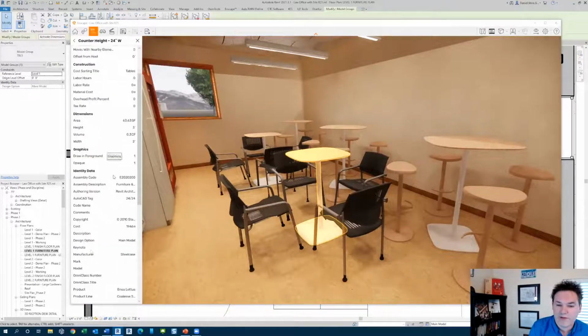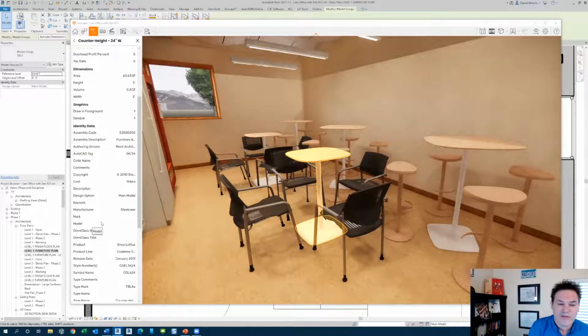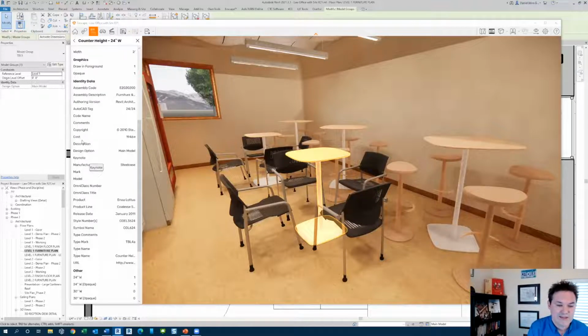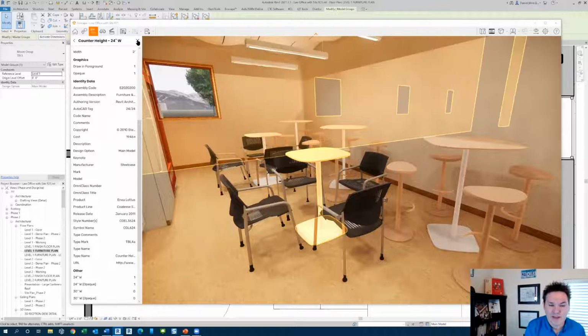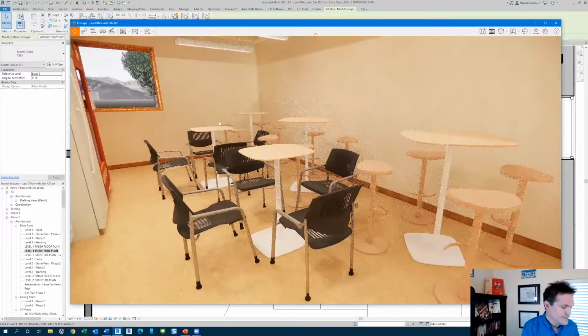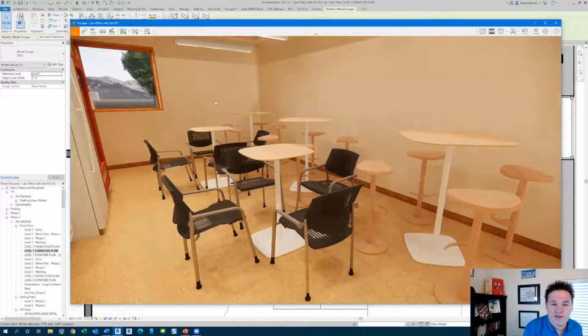And again, we can use the BIM information to verify that. This is a great thing that you can do when you're presenting to a client, if they have questions about cost, if you've embedded cost in here. As you can see, I have $1,946 or any other metrics associated with that particular content.